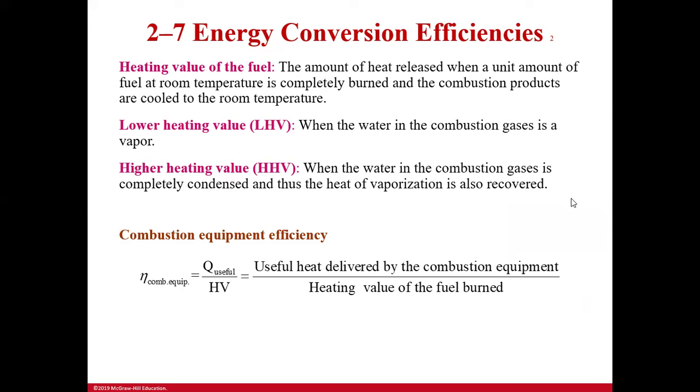Heating value of the fuel: the amount of heat released when a unit amount of fuel at room temperature is completely burned and combustion products are cooled to room temperature. You have a lower heating value when water in the combustion gases is a vapor, and higher heating value when the water in the combustion gases is completely condensed and the heat of vaporization is also recovered.